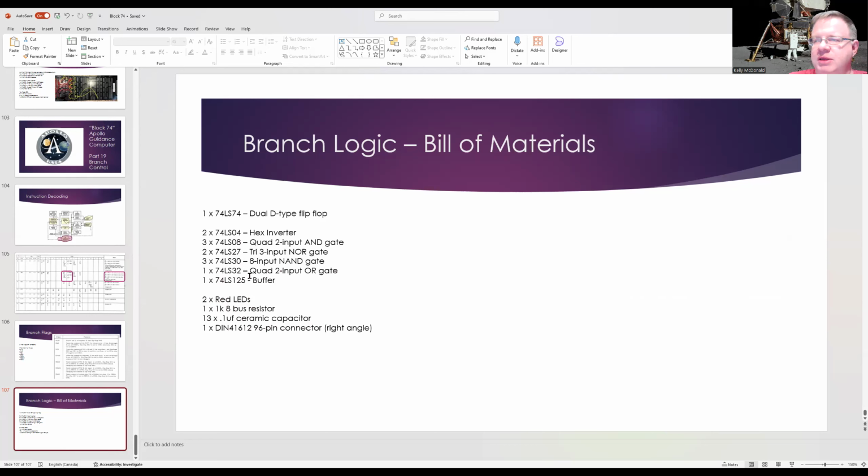This card, the way that I'm building it out, I'm actually also going to use this to display the contents of the write lines itself. So on most of our boards, we've got LEDs that will show whatever the contents of the register are. So I've got some extra real estate here that I'll use this card to actually show the contents of the write lines itself. So I can see what data is being pushed onto the write lines, and making sure that the data is flowing correctly as we start to build up the computer.